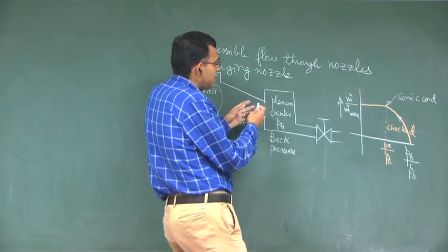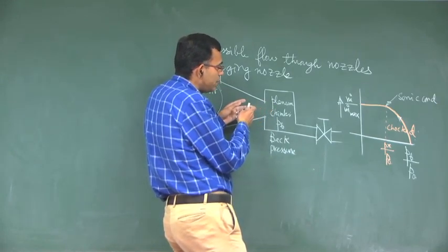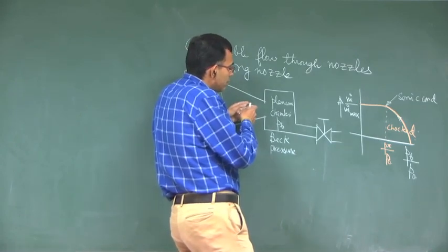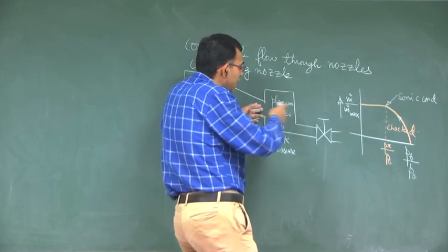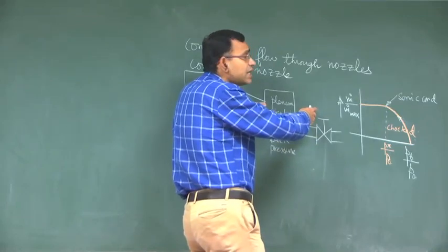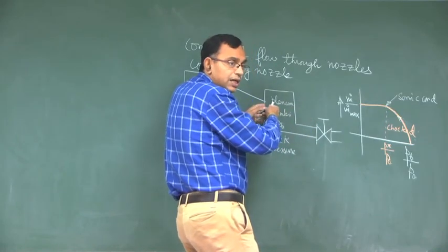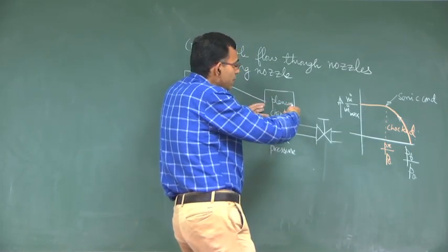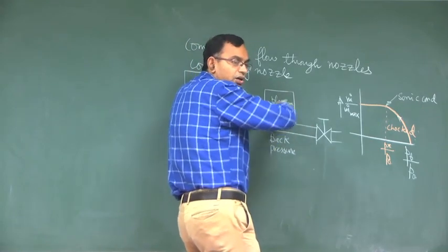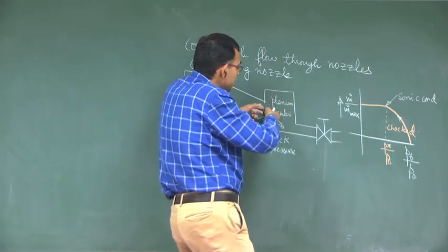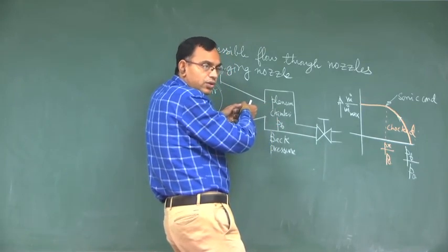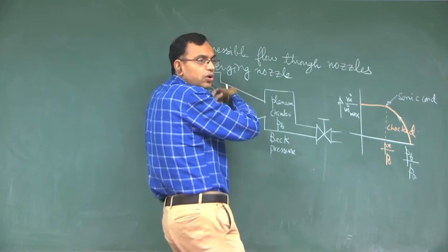So, when the fluid is trying to move with a velocity which is greater than c, that means in this direction the fluid is moving say at a velocity 2c, the disturbance at its best is trying to swim against that tide with a velocity of c in the other direction, but because in the forward direction it is already at velocity 2c, this disturbance against the tide can go only up to c at unit time, but cannot go further.